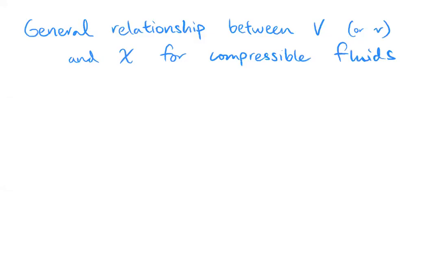In the Roberts example 4-3, we went through what happens with a compressible fluid in this variable volume batch reactor case. And you might have noticed that that was a little bit more complicated for a couple of reasons. One is having to think about how volume is affected by the number of moles in the reactor and how that changes over time in this batch case.